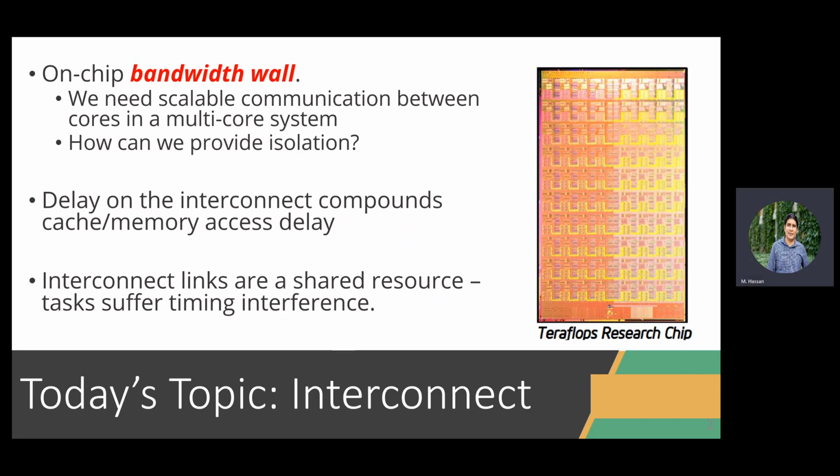It means that given the huge amount of data we need to process, for example from cameras and sensors, there's a lot of data that needs to be stored, transferred and processed. And we are no longer limited by the core running frequency, but instead by how fast we can transfer data and store it, which is basically what we call bandwidth. Bandwidth is simply how many bytes are being transferred per second.